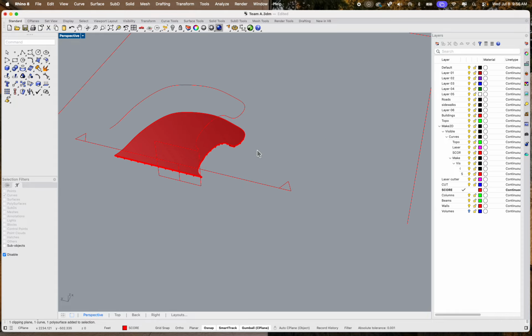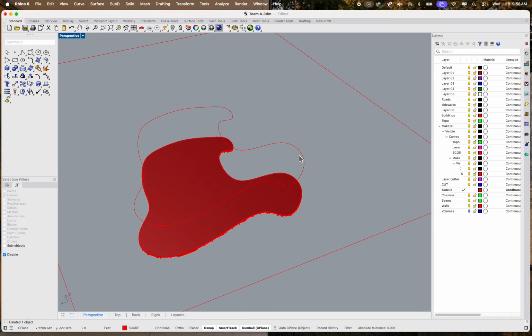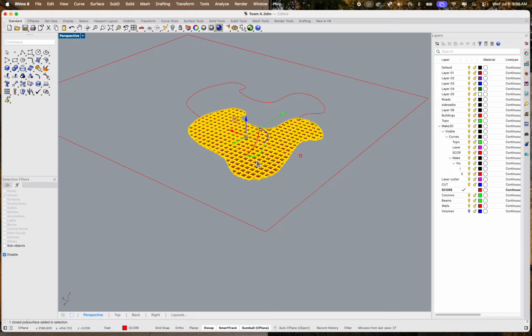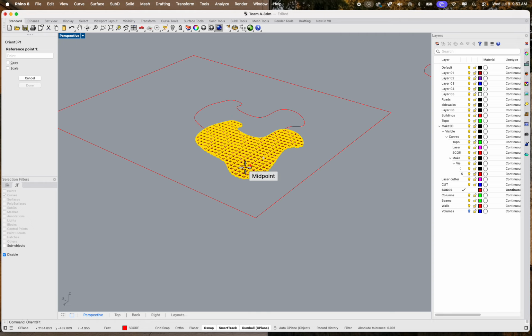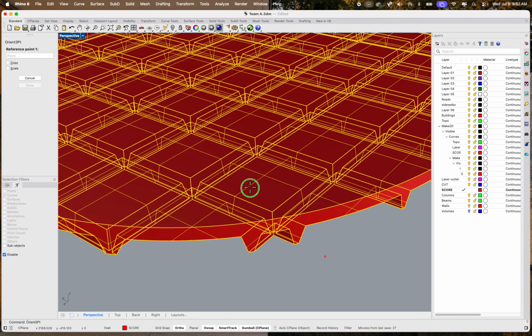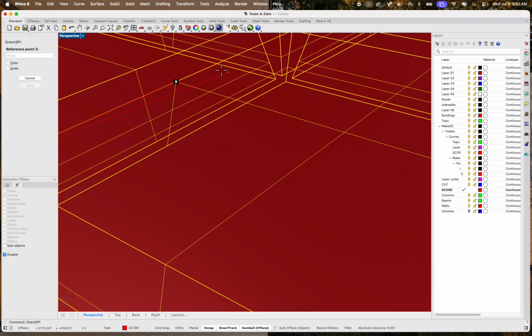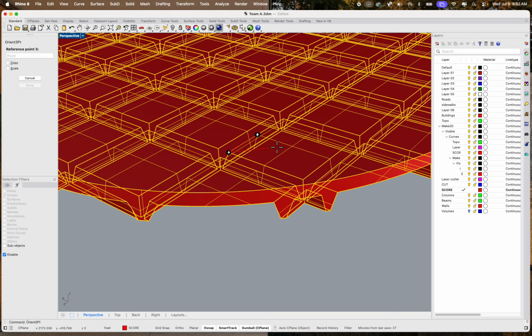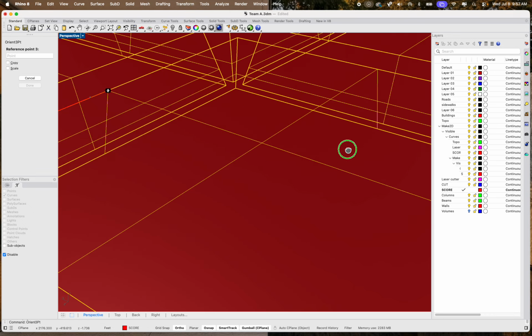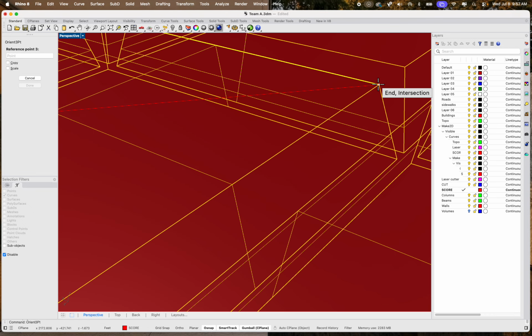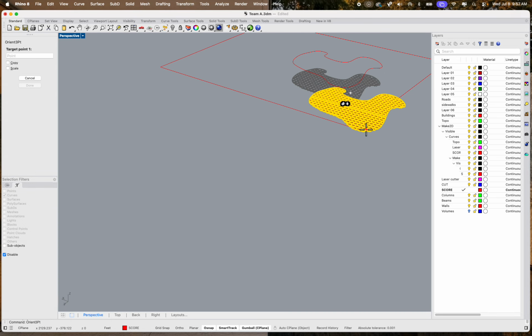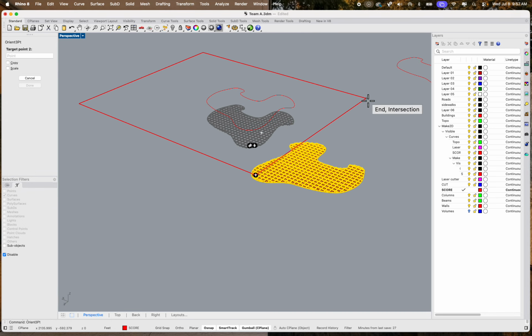But you may run into the same problem, so let's at least cover how to fix it. We'll take that same shape, 3D orient, or orient is usually what I put in first. And then there's two options, orient 3 point and orient 4. We have to choose familiar points, so again, it just has to be 3 points, 1, 2, and those 3 points have to be within the same plane, right? So I chose those, and my last one will be right over here, right? All on the same plane. But again, lock on to a device.